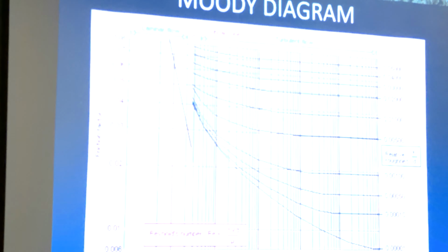Okay, and then these blue lines, these are different types of pipe. And you can classify a pipe based on its relative roughness, which is how rough is the interior of the surface. Okay, so these are different pipe roughnesses, and really plastic pipe and the like, they're all very smooth pipes. So this is the smoothness of the pipe. So this is the line you're working with.